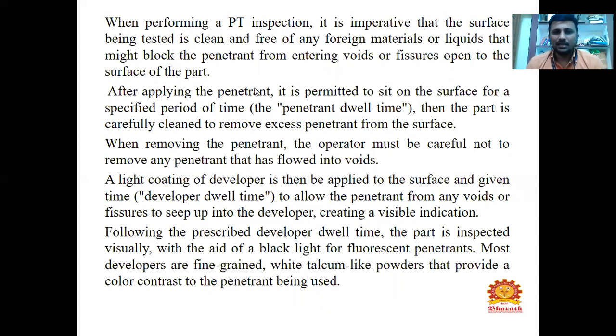After applying the penetrant, it is permitted to sit on the surface for a specified period of time. It's called the dwell time. So a very important point in this testing method is dwell time. We need to apply the penetrant and let it sit on the surface for the specific period of time.